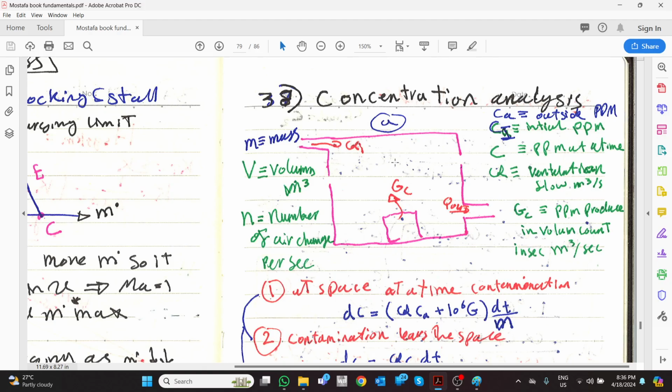Like what? Like CO2. You know that the CO2 outside is 400 ppm, and maybe the CO2 inside reaches 800 ppm, so you increase the ventilation to reduce that CO2. And you know there are persons living or sitting in that hall and generating CO2. This is an example.